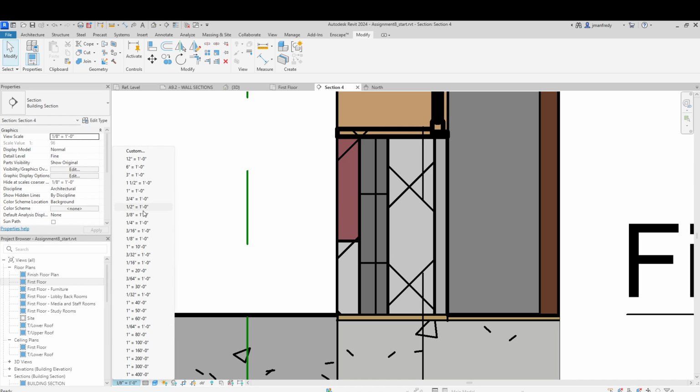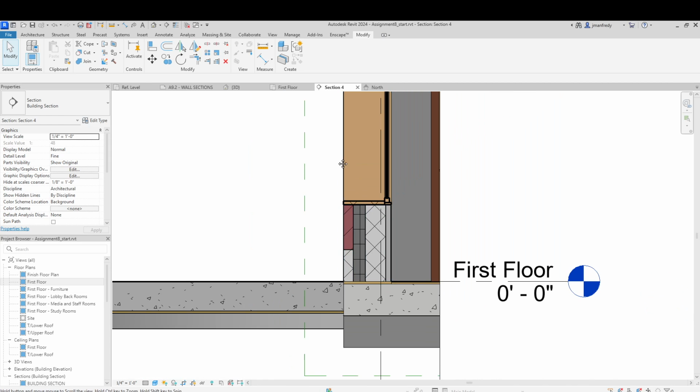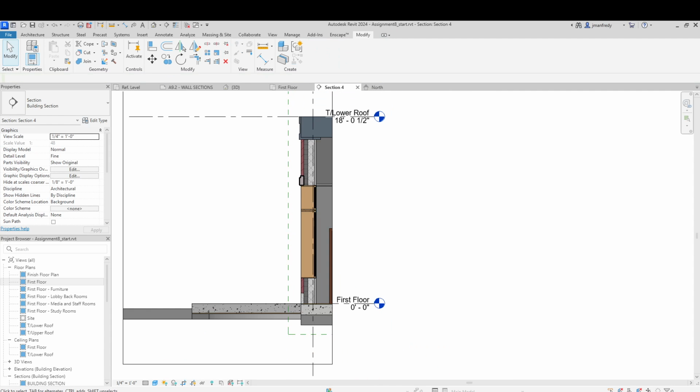Let me change the scale here. That'll change the design you're after from one material to the next. As long as the thickness of the wall, the layer of the material is exactly the same, that's all you're after, it will change the materials in that fashion. Otherwise, you'll have to embed a detail like this as a wall sweep into the wall. This is deleted. Okay? And that's all there is to it.